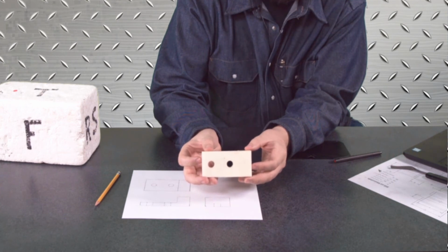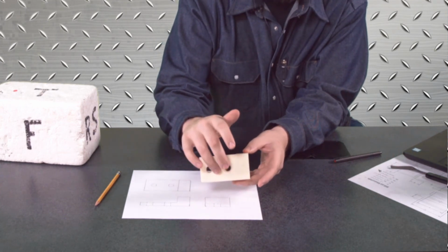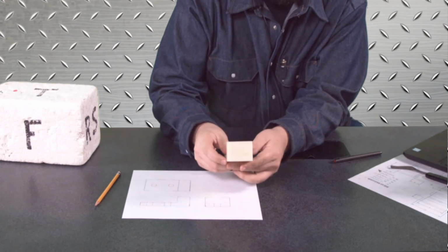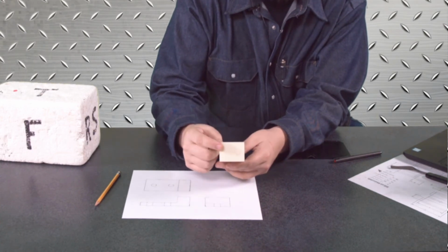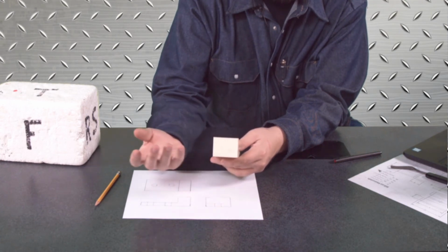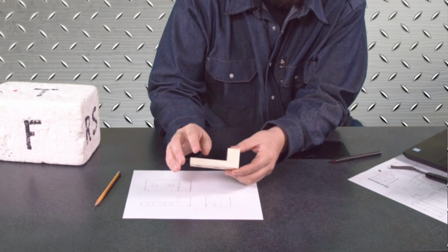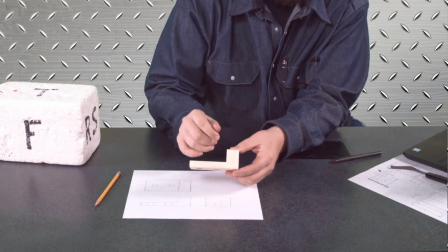If you use this as the front view, that doesn't work out because all you'll see is a square with 2 holes in it. You choose that as the front view, that doesn't work out either because again, all you would see would just be a square with a few hidden lines there and be really confusing. But choosing this to be the front view lets us know that the part is L-shaped.